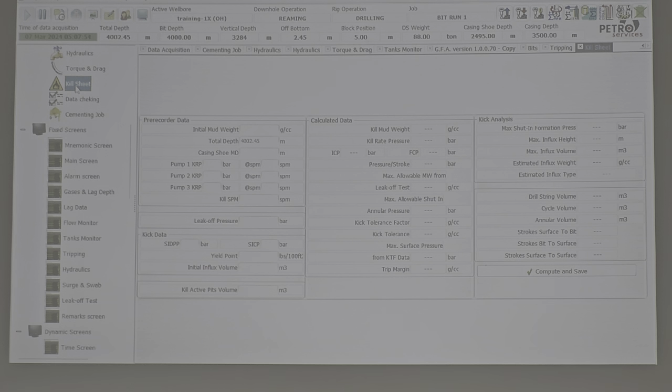What is the slow circulation rate? At midnight before changing drillers, or it's commonly happening, no drilling, they pick up after a connection, normal situation, no gain, no loss, everything is fine, they open the pump at 30 strokes.